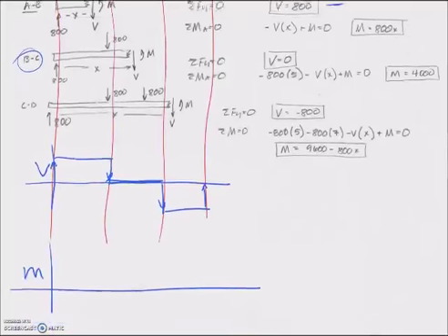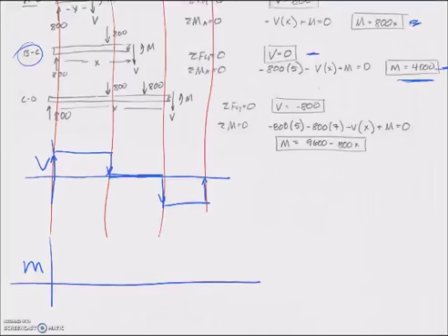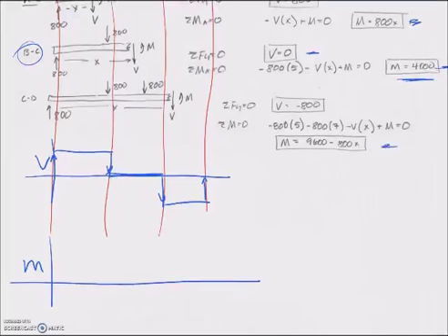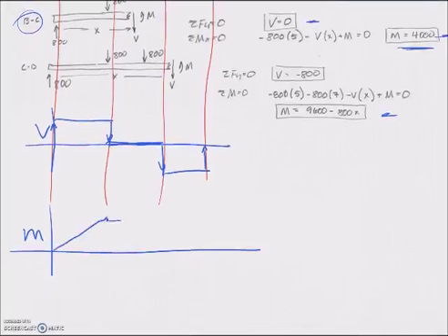All right, what's the moment graph look like? Again, it looks like it's increasing linearly here. Where shear is equal to 0, then moment doesn't change. So moment is a constant here, and then it has a linearly decreasing picture. So it looks like this, flat, and then down like that, where these are going to be lined up like that.